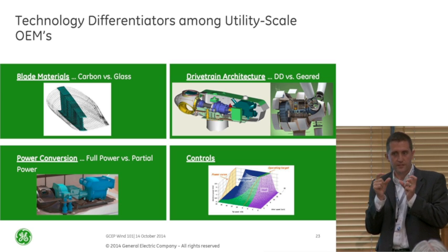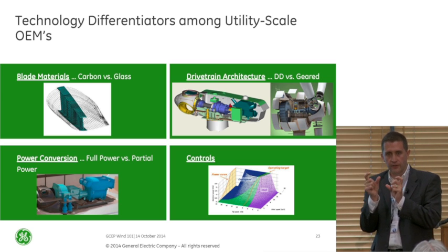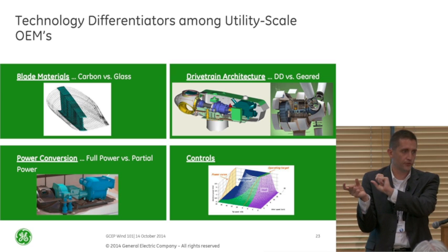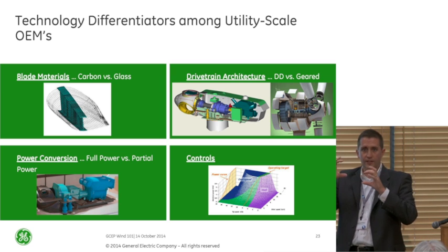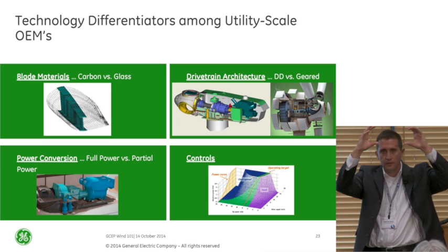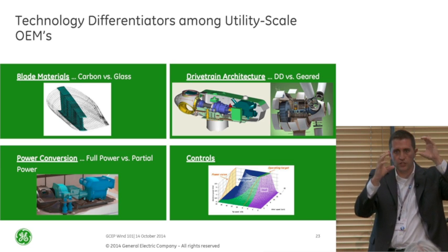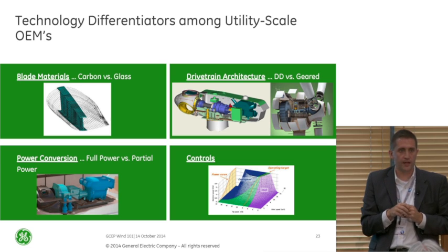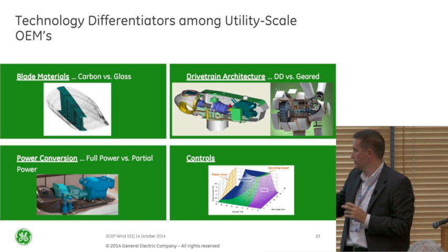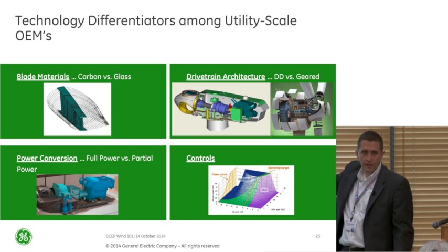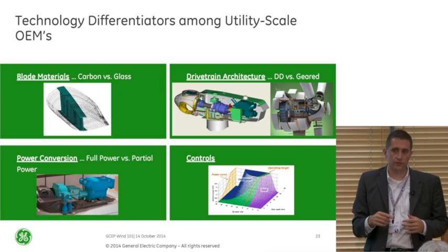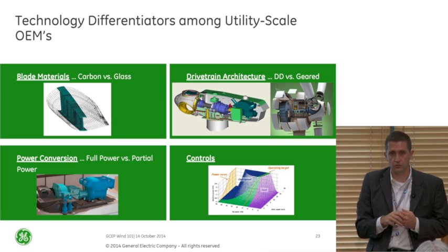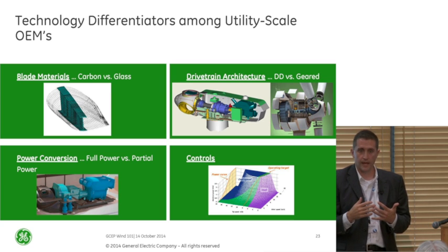And not only the efficiencies of the gearbox and the generator, but now do I have different power conversion efficiencies that I need to transfer through the whole system? Now have I changed the mass up tower? And I have done that, so now I might change my foundation and my tower's design. So it really propagates through in terms of not just the gearbox versus the added cost of the generator. You need to go through efficiencies, you need to go through the loads it's going to see on the rest of the structures. So it really becomes a lot more complicated.